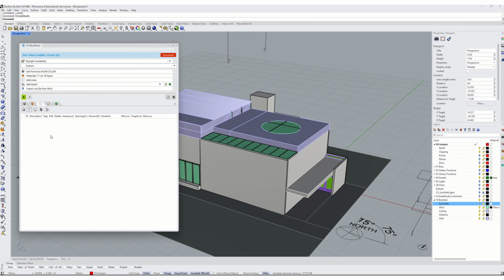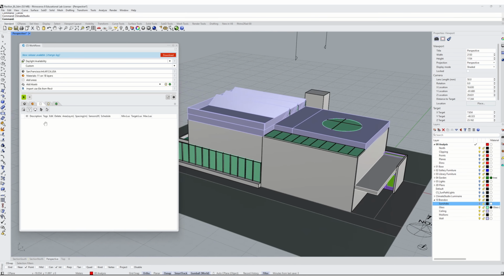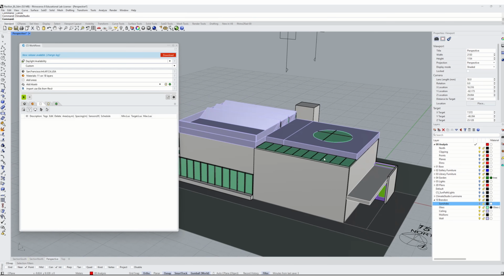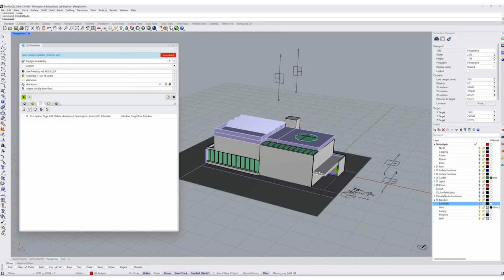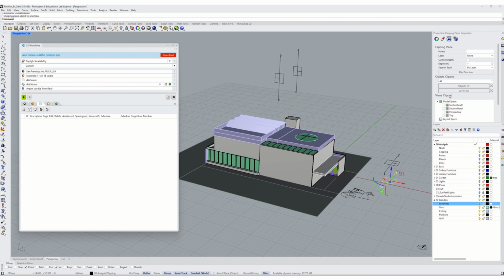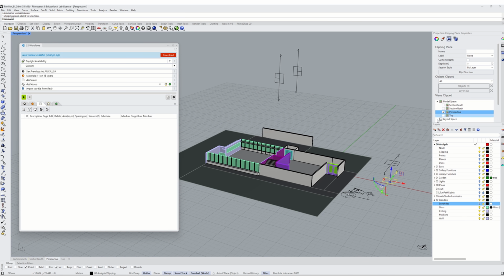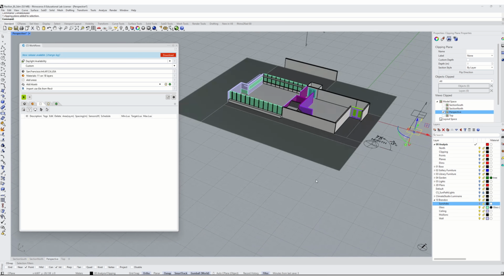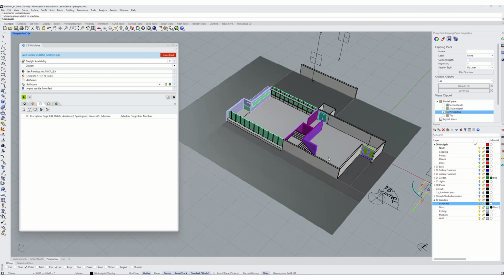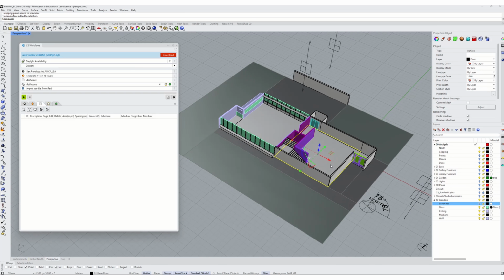And this is a new part of this analysis, is going to be defining some analysis planes. And these planes are commonly work planes. In the case of our gallery and reading room, we're going to use the floor as a proxy for how much light is around the space. This is kind of an imperfect proxy, but I hope it's a straightforward way of getting into this set of simulations and understanding the nuance of it.